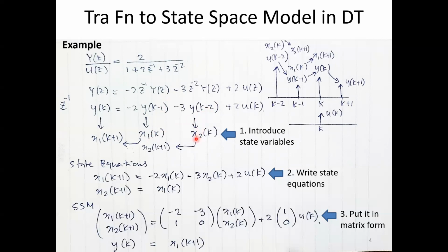From now on, we don't have y. We call the most recent one x1, and the signal two steps back x2, and we call them at the same time k. Now all the signals on the right hand side are converted to time k, the same time. So you're taking signals from the past and giving them a new label like x2, and saying it's present time. It's like taking expired stuff, rewrapping it and putting it on the market under a different brand. State variables are all samples, but you give them a new look, x2, x3, and so on, like fresh variables at present time.